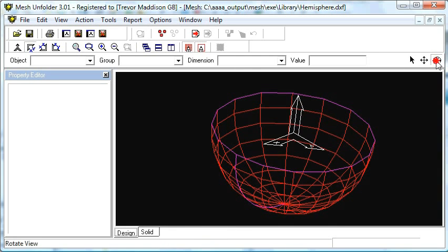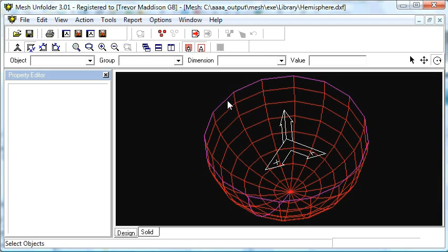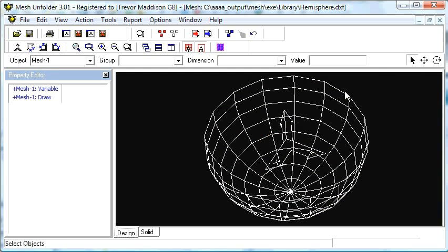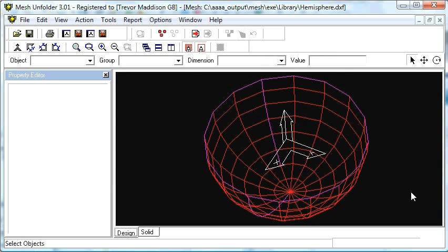So we can do things to improve that, perhaps as you would in dressmaking. You make darts and that kind of thing. Let's make a dart by selecting the node mode and selecting a strip that we want to split apart. So that becomes a new split.